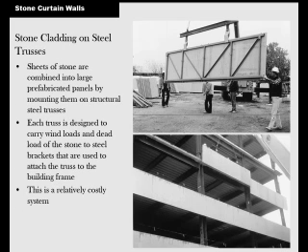Here you can see how they would strengthen it. You have to strengthen it if it's a thin piece of stone, so you'll put some steel stuff on the back of it just to make sure it's stiff and doesn't buckle or break, because it has to be designed to the wind loads, and they hoist it into place, just like we saw in that movie right there.